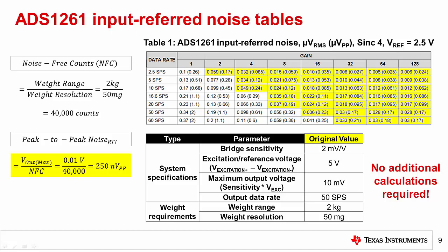If you wanted to know the noise-free resolution at a different data rate, or even how fast you could sample, you would have to calculate the resolution loss for these new values as well. This makes noise analysis with relative parameters less adaptable to system changes and confirms that input referred noise is a better choice for ADC noise analysis.